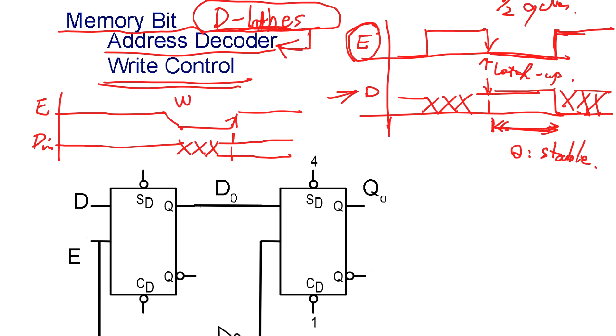This is called write enable pulse. And the write enable pulse, the trailing edge is a latch up point. The data in has to be stable before that trailing edge. Okay, then it latches up the data. Then it stays disabled. This is bar disable. Then the memory content is held forever until the next write cycle.